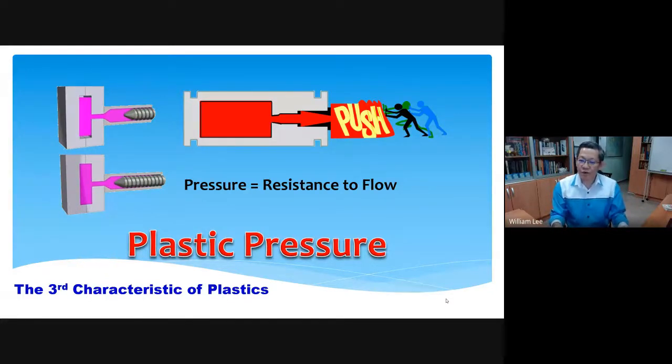And for this reason, one of the functions is that after you fill, you squeeze in more material, you pack the material. Now you need to introduce pressure to the plastic because when plastic changes from liquid to solid, it can shrink as much as 20 to 25%. If they shrink more, you get a smaller dimension, right? So therefore, you need to provide them this pressure.